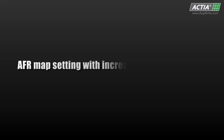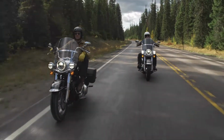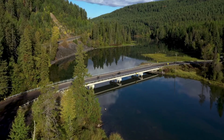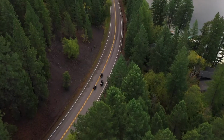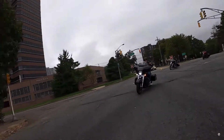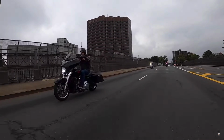Adjusting the AFR map for improved driving comfort. A general requirement on the part of bikers is driving in low RPM modes, where the V-twin engine has the best sound. However, shifting at low RPM causes the engine to temporarily enter into an unstable operating mode. Therefore, it is best to set the very low RPM region of the map to a rich mixture as indicated here. In these cases, the changes in the emission behavior of the engine are minimal, but driving comfort increases significantly. This setting even allows using higher gears at very low RPM.